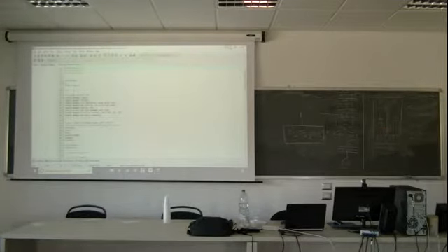Yesterday we had 3 different types of nodes. Node number 0, because it was at the base, had one equation. A node in the middle, between 1 and 6, has another equation. Conduction, conduction, and convection, right? And the last one was different because it has no conduction to the east. Do you remember? Now, how many different nodes do we have?